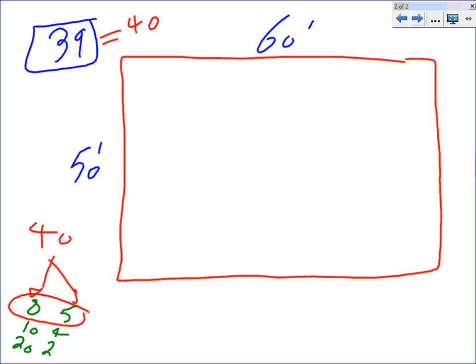So, okay, any question why I came up with 8 by 5, not 20 by 2? For example, 20 by 2 will be a bad design. So you have 2 rows and 20 columns in between. It works, but the light distribution is not the best. The light distribution, guys, is the best if you end up with the same number of columns and rows. Okay? Obviously, I can't in this situation, so I have to go by 8 by 5.